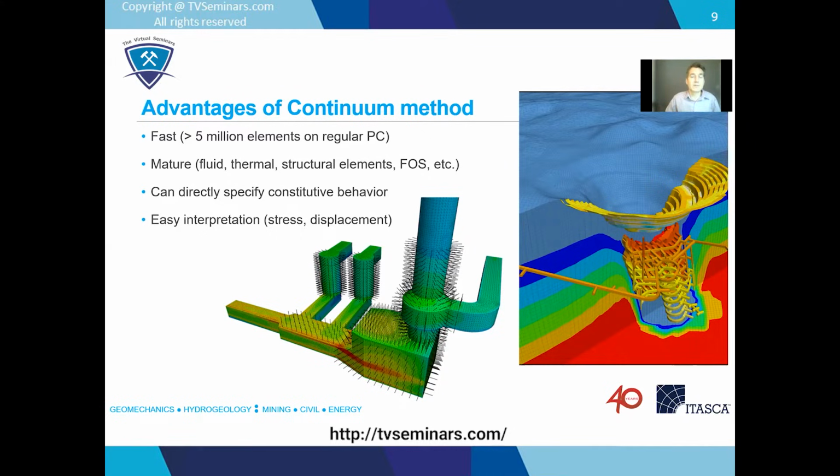You can directly specify constitutive behavior. This is very attractive, especially in soil mechanics, where people have very specific and very complicated soil behavior. And lastly, I put here easy interpretation. People like to see these contours of stress and displacement, like I'm showing here. You can slice it and dice it and get cross sections, and all these kinds of visualizations are relatively easy with the continuum method.